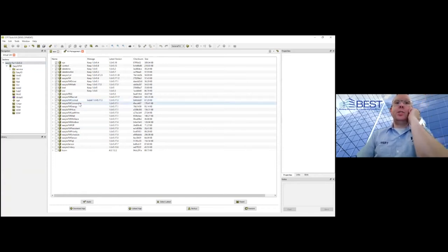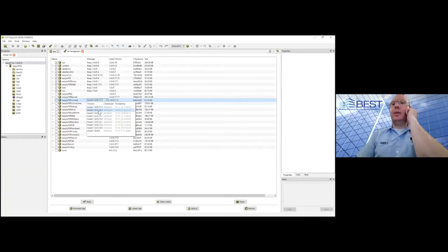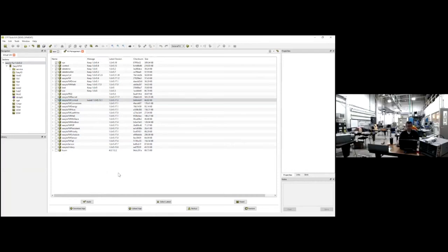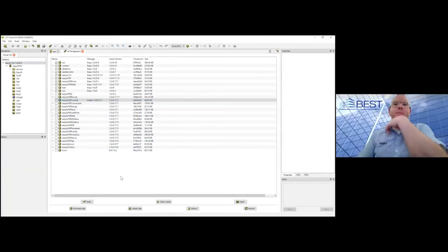Notice where it says install version. If you click on that version, you can hit a drop-down menu. And you may be able to find one of those other versions and select it. And that red may go away and your apply should come back. Yep, worked perfect. Awesome.